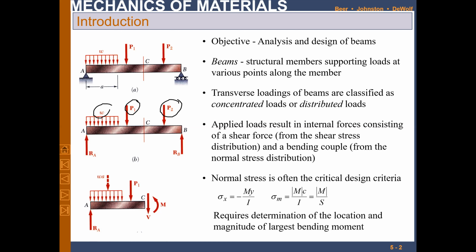This is what we already know, that sigma x is minus My over I from chapter 4, and the maximum is Mc over I, or M over the section modulus. This is what we already discussed in detail in chapter 4, right? So whenever you have, you can see that this is the force, right? And then you have the moments as well in this particular case, right?